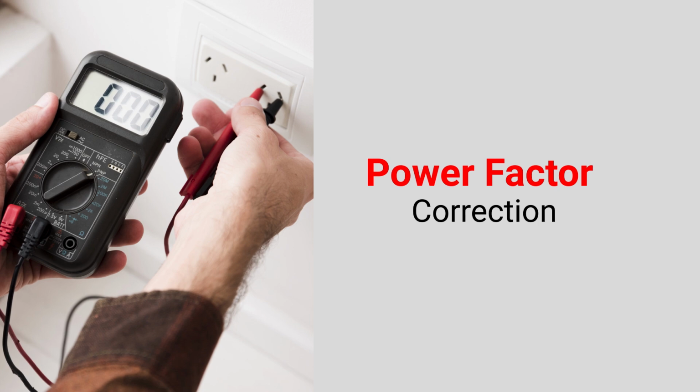Now we are going to discuss power factor correction, how the power factor can be corrected. So as you know, the cause of the low power factor is what? Inductive load. That means current is lagging with respect to the voltage. That means by any means, if we are able to introduce such an electrical component which leads the current with respect to the voltage, that means this leading angle can neutralize the lagging angle.